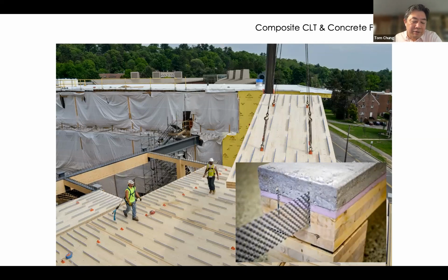so that the wood was not taking on the dead load of the concrete, but would work structurally with the concrete taking the compression and the wood taking the tension. That allowed for a longer span, a more durable floor system, which could then take on the 100 pounds per square foot instead of the 60 or 40 pounds per square foot that was typical in these classroom buildings, and allow for greater flexibility and use of assembly spaces within the building in a flexible manner.